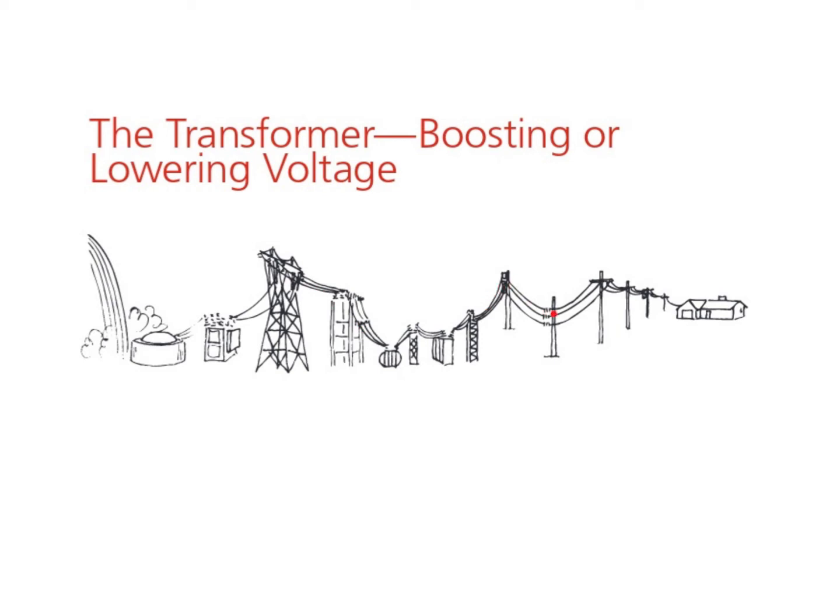The current will travel down these long wires for miles and miles and miles, and then there'll be a transformer near your house that reverses the direction so that the voltage gets cranked back down. Now, over the long miles and miles of cable where the current is very low and the voltage is very high, there's not much heat of the wire, and so you're not wasting energy heating up the wire. I don't know about you, but I would not want to pay in my power bill the cost of making the wires to my house hotter. And so the power company is doing us a solid by ramping these voltages up so that we don't have to spend a lot more money paying for energy that we're not even using.